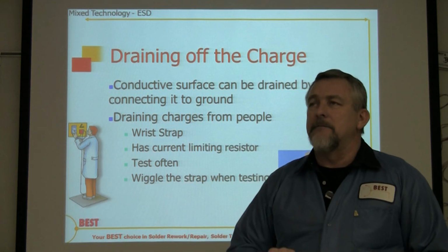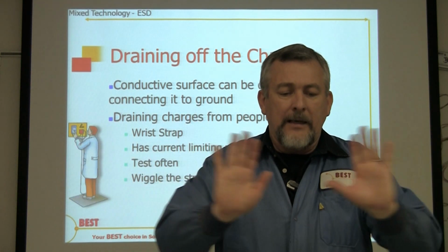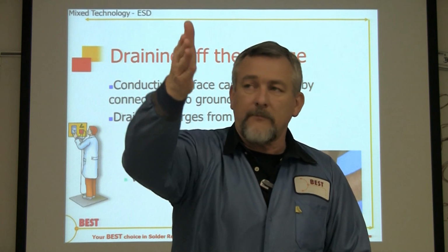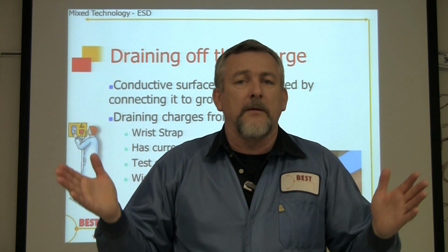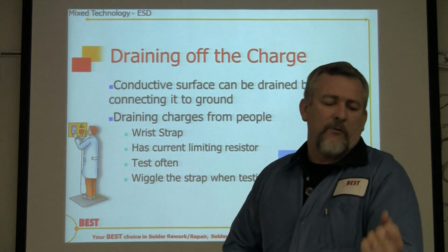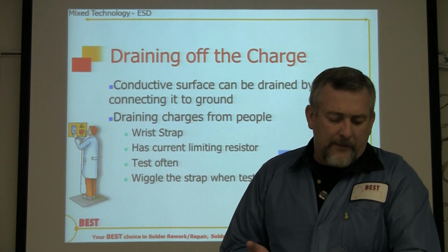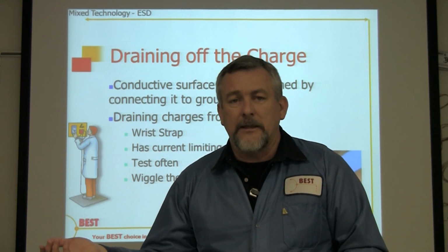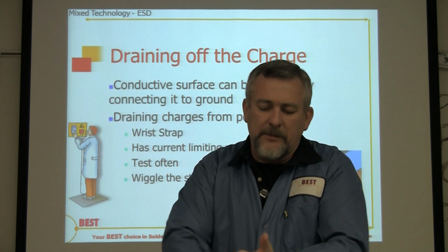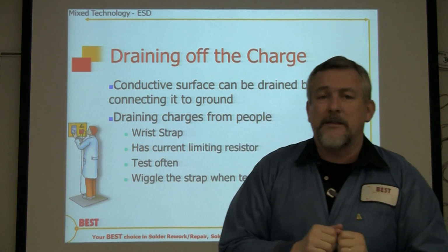I go to companies, prime example, I was in Penang, Malaysia teaching several years ago. And to get in, for their doors to open, you plug the wrist strap into the tester, and then if everything's right, the doors open. Well, believe it or not, mine didn't work. You rotate your wrist around and stuff, and that could be intermittent issues, but it still wasn't working. So what I had to do was take this lotion that they have, ESD safe lotion, like a hand lotion type material, and I wiped it all over my arms and my hands, and I did it again. Well, guess what? The doors opened for me. So that's what you got to look for, is stuff of that nature.